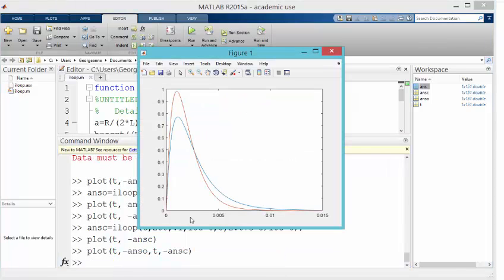show you the result. Okay, so the overdamped case is right here, and the current does not reach its current maximum. So it's the blue line. And in the critically damped case, my current can reach a higher value. So the current maximum is higher, and then also notice that the decay is quicker.